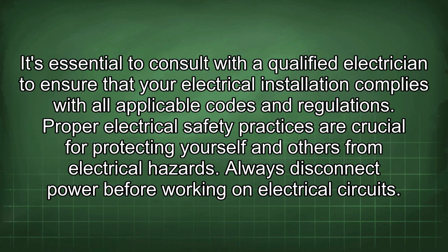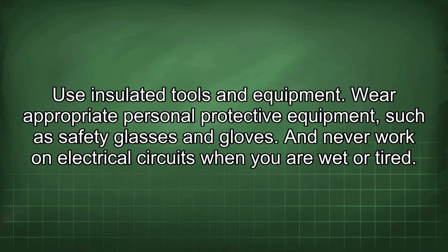Proper electrical safety practices are crucial for protecting yourself and others from electrical hazards. Always disconnect power before working on electrical circuits. Use insulated tools and equipment. Wear appropriate personal protective equipment, such as safety glasses and gloves. And never work on electrical circuits when you are wet or tired.